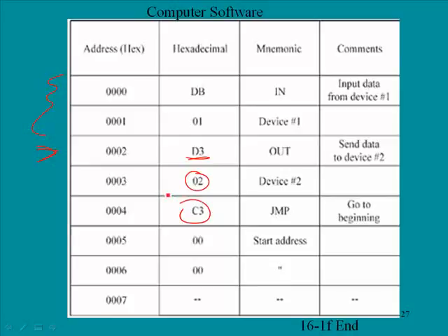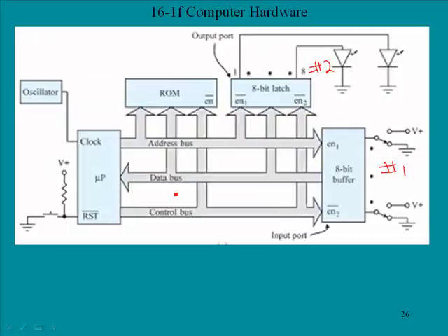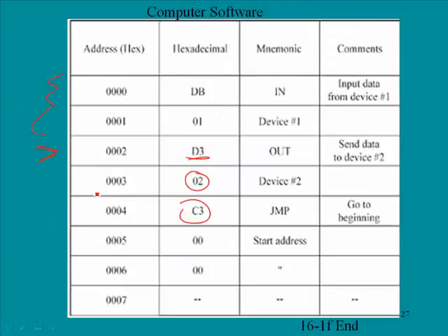This byte is loaded into the instruction register and decoded. Upon decoding, the microprocessor determines that this is a 3-byte instruction, so it must access 2 more memory addresses. The program counter is incremented, the memory is addressed, and down the data bus comes 00. That's our next byte. The microprocessor holds this in a temporary storage register.